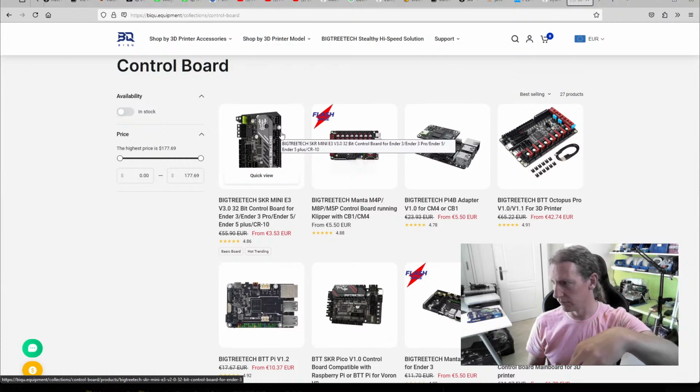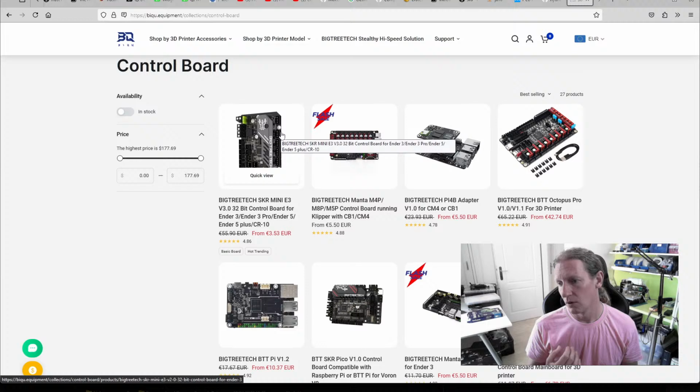And then in order to let go of a component, they often have just an air pump essentially, which goes through the same lines, or rather, it switches the air going to the nozzle from a suck to a blow. So basically there's an actuator that you need which can do that. It's either on suck or it's on blow. And they need to be fairly fast acting. And they're normally just triggered by a general output from a MOSFET or something like that.